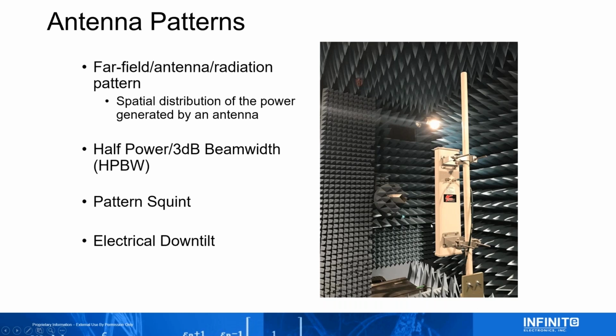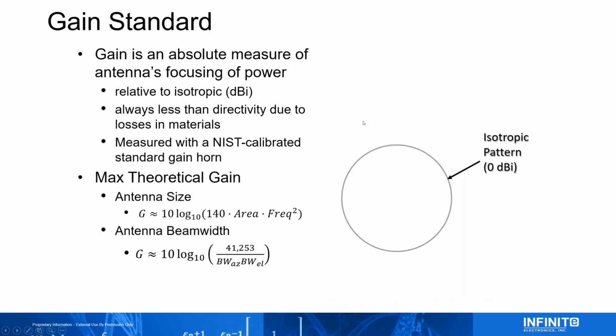I already spent too long on this, but here's how you measure antennas. One way to measure it: this is a near field anechoic chamber. It's a cylindrical scanner, and here's a sector antenna mounted on a fiberglass rod. And then this is a waveguide probe, and this just rotates around its axis, and then this stays fixed and measures the pattern.